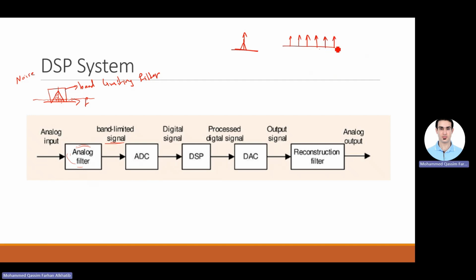Okay, sampling happens in the time domain. So I assume that I have a certain analog input signal, something like this. This is the signal. To sample it, I just multiply it by a train of pulses. So this is sampling.